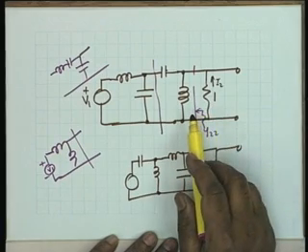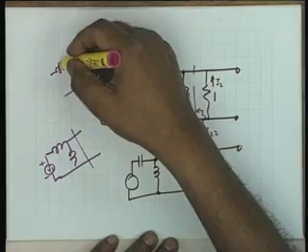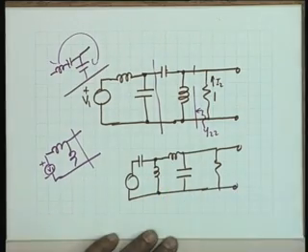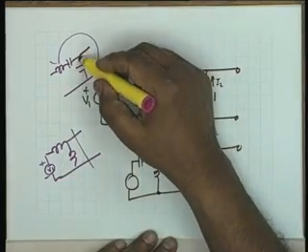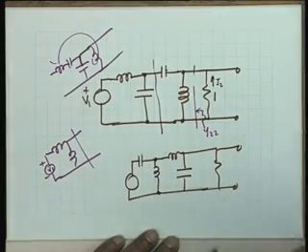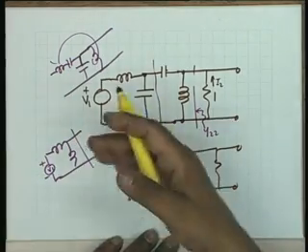So this will come when we have one transmission zero at S equal to infinity and then 2 transmission zeros at infinity and 1 at the origin. Can it be like this? The first is a capacitor in series, then an inductor in series, then an inductor in parallel and a capacitor in parallel. That can also be a perfectly valid structure. Why not? If there is one solution to a synthesis problem, there is an indefinite number of solutions. But of course, solutions have to be reasonable. I mean, they have to satisfy the original specs.